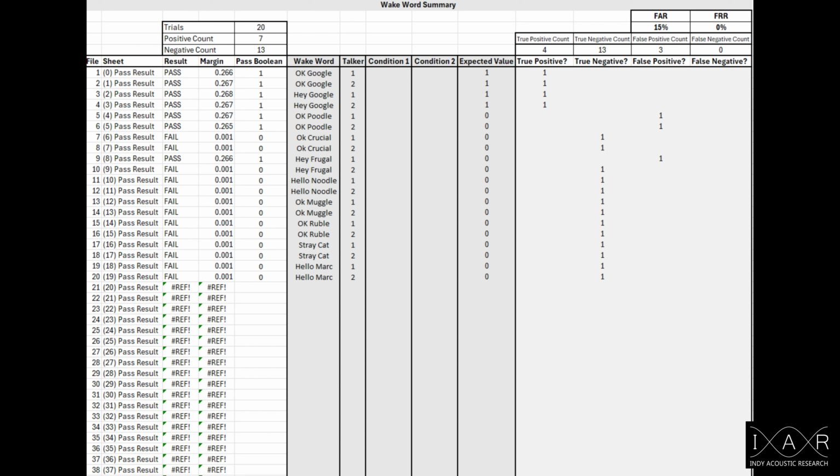We still call these FAR and FRR, but technically, as per the earlier definitions, that's incorrect, as those definitions were expressed as a count of incorrect responses per hour, not a percentage of the total number of utterances. But the intent is very similar, and if we also specify the number of wake word attempts per hour, then we can convert between measures.